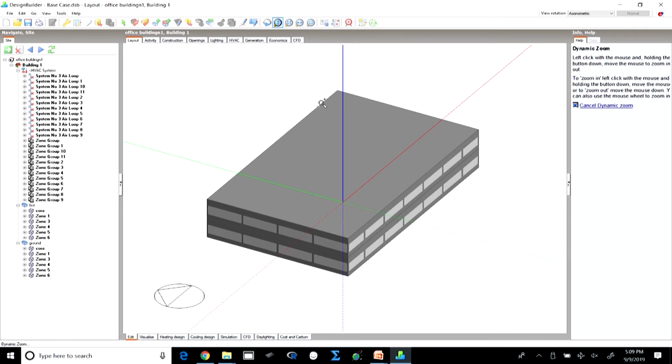Here in this case, since the building is rectilinear, it will not make much of a difference, and we can average out of 2 as well, because it is uniform. However, if we are doing an irregular building, then we simulate it for all 4 major orientations and then calculate the average overall electricity consumption, energy consumption for the building by taking an average of the 4 base case buildings.